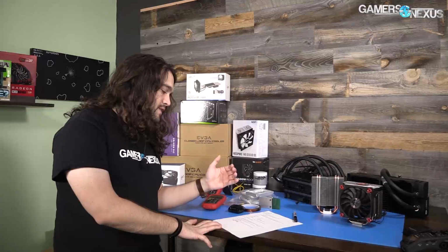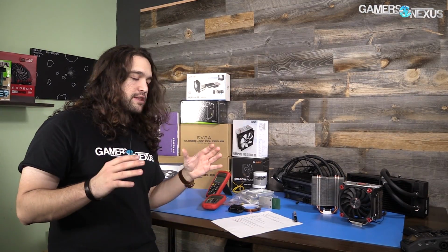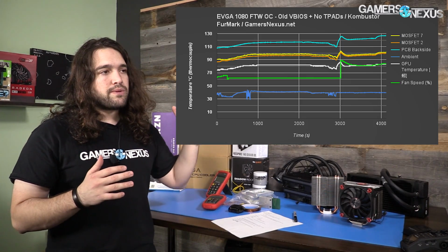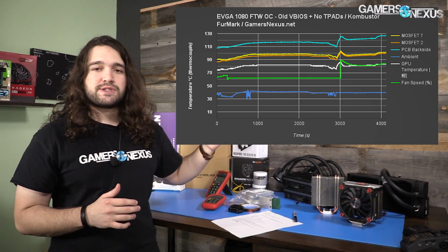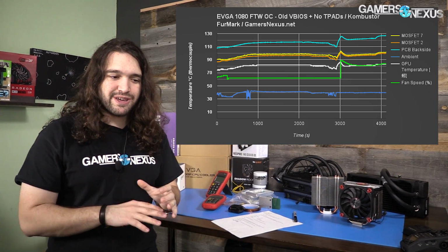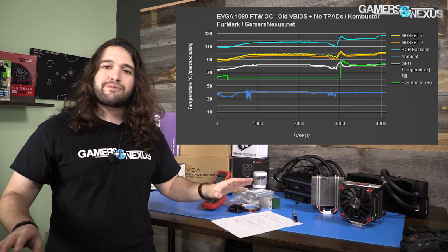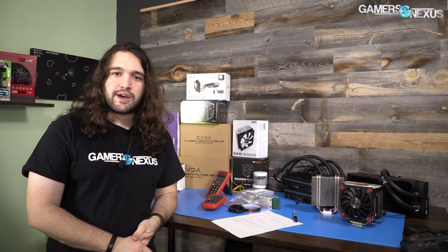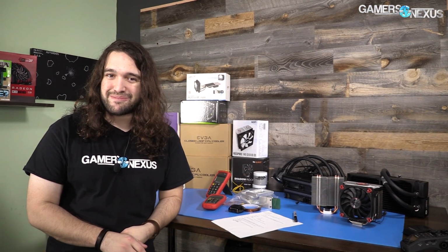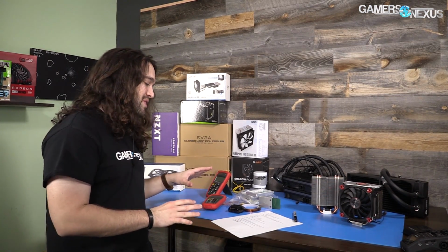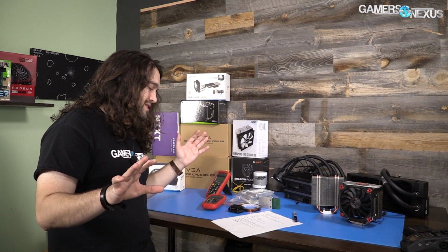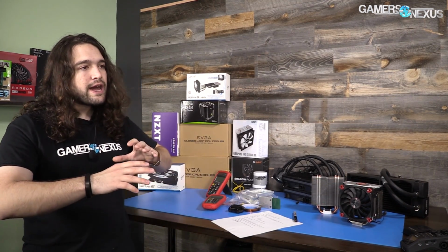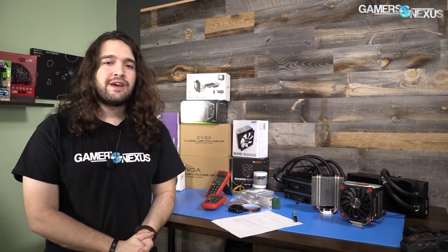But back to Kyle's stuff. So GPU, the back of the GPU can radiate heat. When we tested the EVGA cards for VRM temperatures, we saw that we were able to get the backplate of one card up to something like 130 Celsius when we really, really, really tortured it beyond any reasonable measure by dumping 40 or 50 degrees Celsius air straight into the VRM fan from a liquid cooler. So the point is, the back of the GPU can radiate a lot of heat, and depending on how your cooler is oriented, that can impact the CPU temperature.